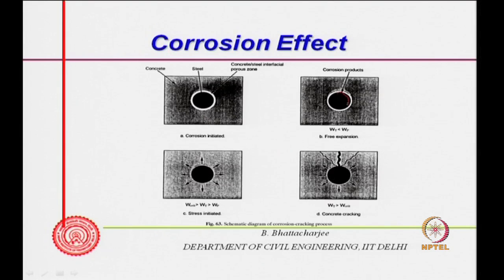First it fills in these pores, exerts pressure on the surrounding concrete, and finally causes cracking of the cover concrete. So, general corrosion results in cracking of the cover concrete, and this can happen from carbonation or chloride coming from inside, as an ingredient. But for external chloride, sometimes you may have pitting corrosion. If the chloride has gone to one place and not another, a pit will form at that location, and the rebar may even be lost totally.